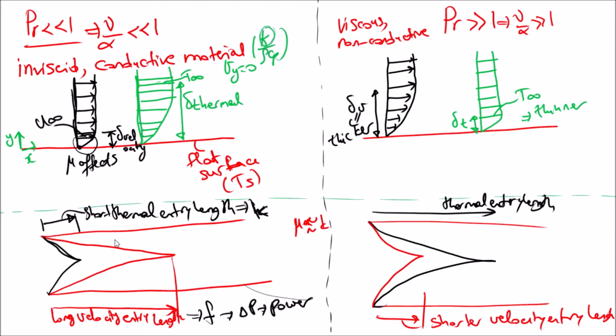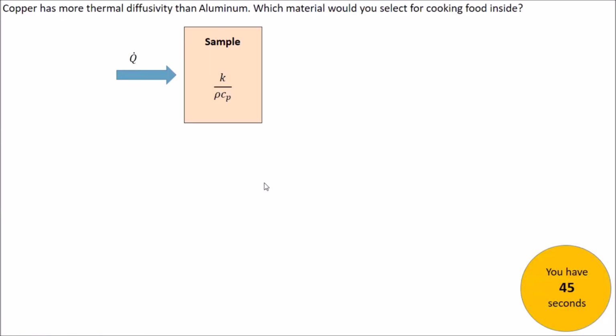Yeah. And we know that mu is very similar to K. Okay, so mu distributes momentum in the y direction, and the K also distributes the heat in the y direction. Okay, and this one is dominated by K, and this one is dominated by mu. Okay, so they have similar properties. This one distributes momentum in the y direction, and the K distributes heat transfer in the y direction. Okay, but they are all distributing x direction values in the y direction. Okay, this is the importance of the Prandtl number.